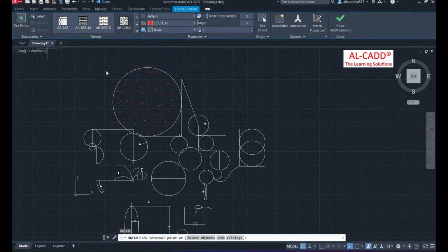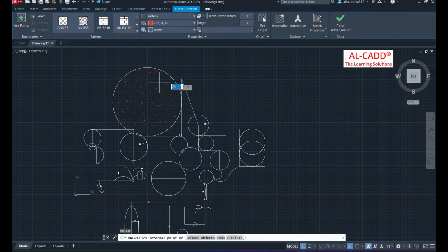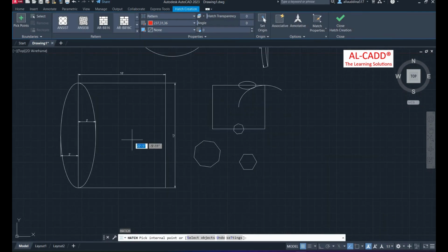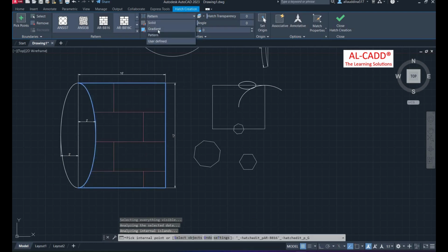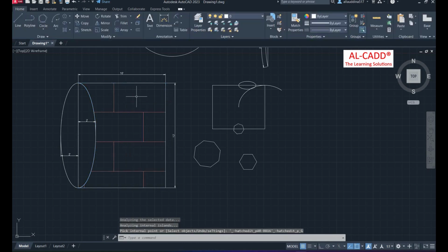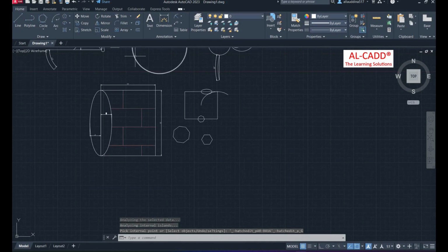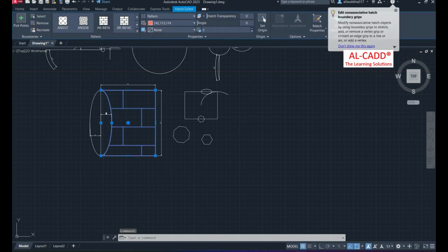Now if I take this hatching called brick, now I have taken the brick. Now if I'm going to assign it to this, if I click, now see the hatching pattern is applied. If I select this and the pattern, then you can just select here. Like this, you can do it here. And after this, if you want, you can change this pattern and select another hatching.